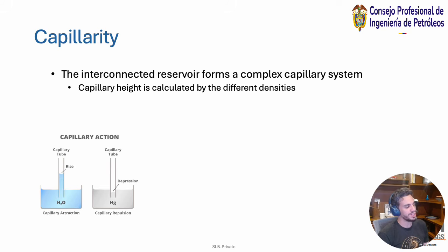So when we're talking about capillary, this diagram shows something relatively cool because, again, when we think of capillary pressure, we think, first of all, pressure by dimensions is some sort of force over area, right? And what capillary pressure is rewriting the equations for pressure in terms of height and density. So density, so rho gh basically, so density times gravity times the displacement or the delta in height will tell us about the pressure.